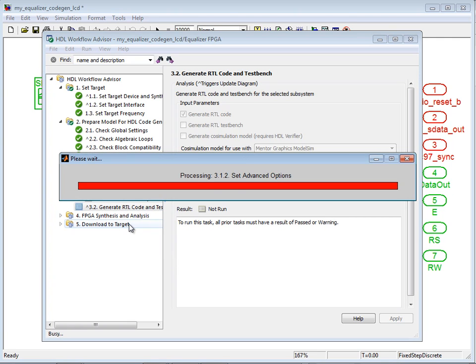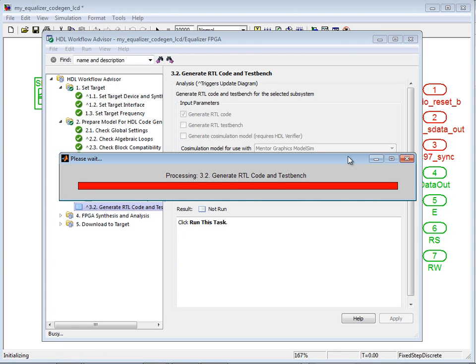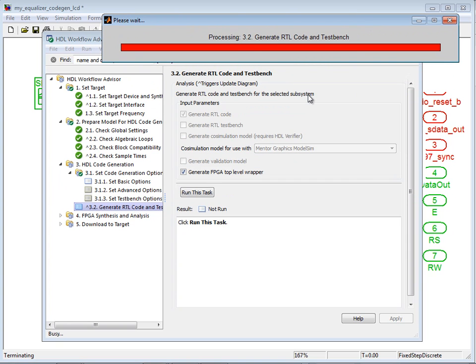So let's generate code, and in this case we will not only generate HDL code from this particular system, we will also generate, as I said, a wrapper file which also instantiates a clocking module which handles the clock conversion, and additionally we will also generate a user constraint file which constrains the FPGA implementation tool to connect the I/O of the Simulink model correctly to the correct FPGA pins. So let me just show you this.